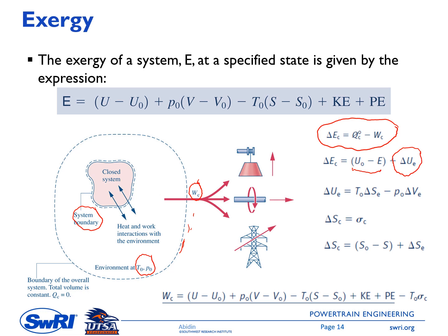Okay. And then from one of the entropy correlation in chapter 6, we have this correlation between delta U with T delta S and P delta V. Okay, so review it, chapter 6. So in this case, I have the delta UE equal to T0 times delta SE. So delta SE here is the change of the entropy of the environment minus P0 times delta VE. So this is the change of the volume of the environment.